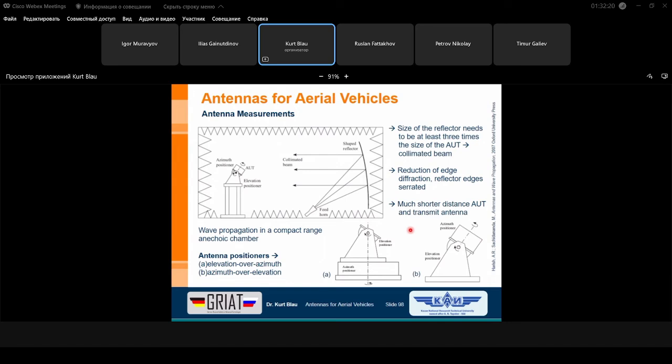The working frequency of an antenna is, for instance, in the range of the bandwidth of the antenna. The bandwidth is determined, for instance, by the voltage standing wave ratio. This is, let's say, a more or less international agreement, with a voltage standing wave ratio of 2.